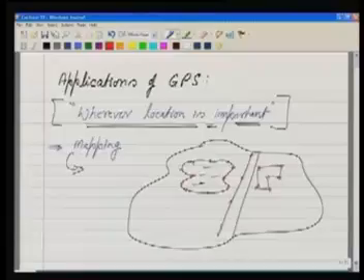So once I'm occupying these locations, what I'm getting the coordinates, and then later on I can go to any CAD package or any plotting package, or maybe simple drawing sheet, and I can plot those coordinates, join them and give the proper legend or the symbol. For the house we'll give the symbol of the house, for the water body symbol, and so on.